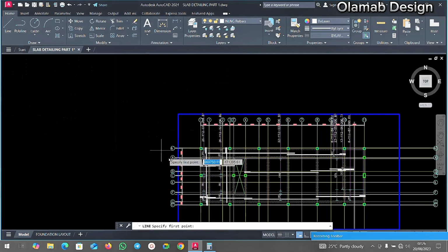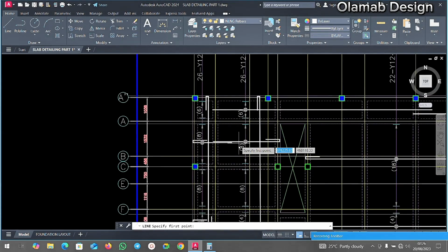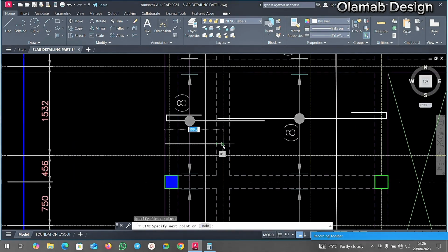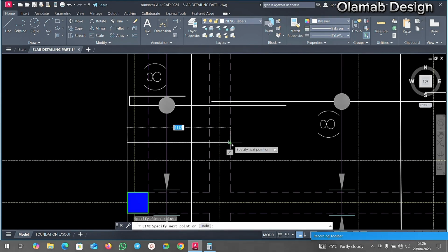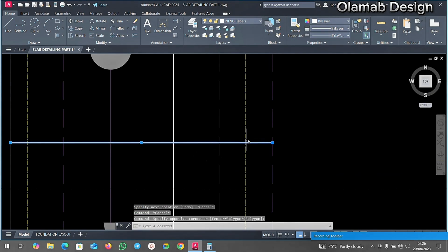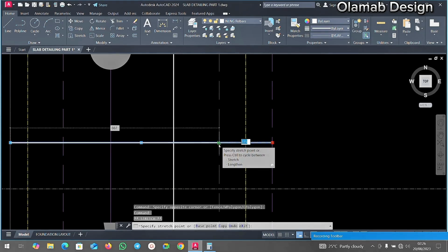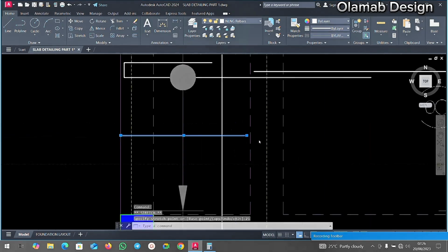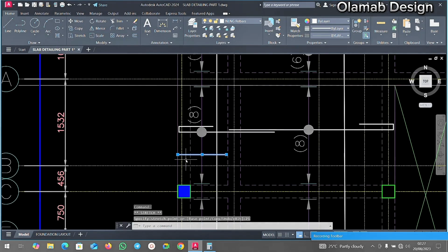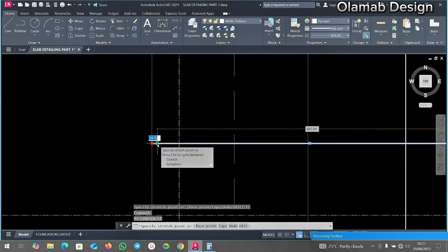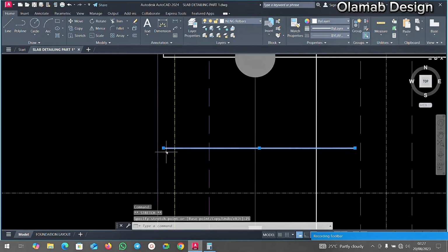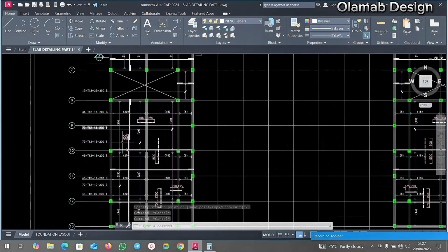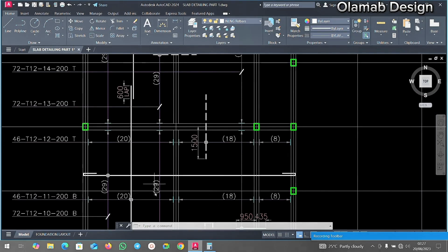And we can pick our line. Let's draw our call out line. Pick this and stop this right, let's see, can stop this here first. Take this, take it inside to the edge of the beam, then take it inside by 25, hit on enter. Then also here, take it inside by 25, hit on enter. Then take your indicator. I'm going to pick my indicator. Let me say I'm going to use this one, okay.